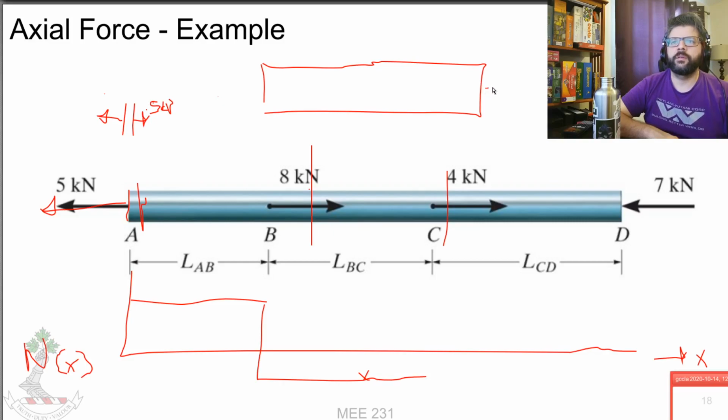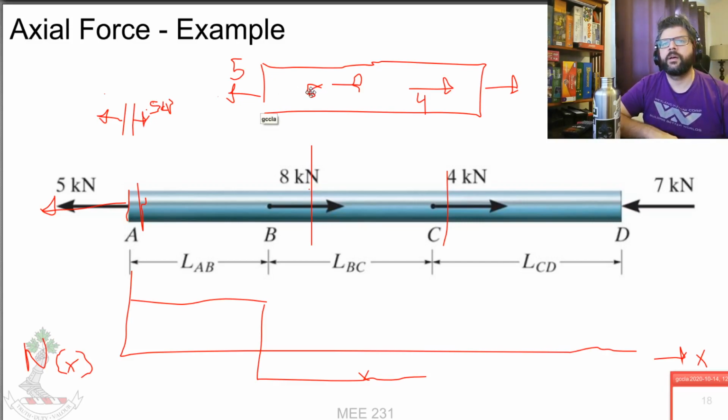So again, we'll draw our N. We've got a 4, an 8, and we've got the 5. 5, 8, 4. So taking the sum, N plus 8 plus 4 minus 5 is equal to 0. So solving for N, -12 plus 5 gives us -7. So we're dropping down again.